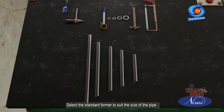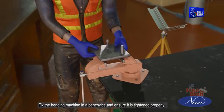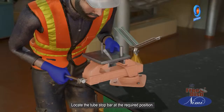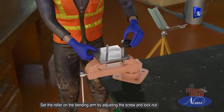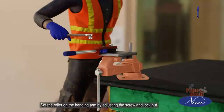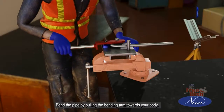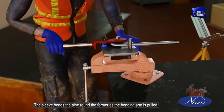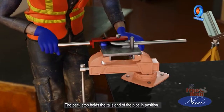Select the standard former to suit the size of the pipe. Fix the bending machine in a bench vise and ensure it is tightened properly. Locate the tube stop bar at the required position. Set the roller on the bending arm by adjusting the screw and lock nut. Bend the pipe by pulling the bending arm towards your body. The sleeve bends the pipe round the former as the bending arm is pulled. The backstop holds the tail end of the pipe in position.